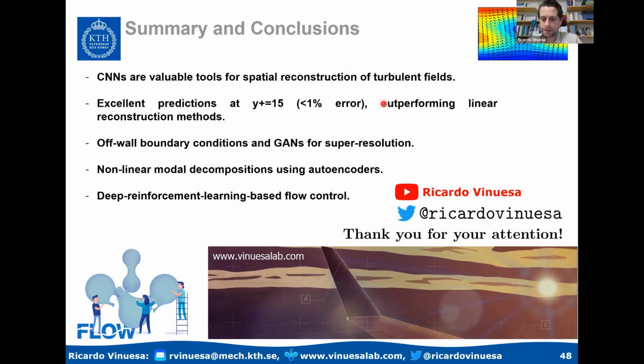Some of these 2D cylinders at high Reynolds numbers that we're exploring become more computationally intensive, because you have many different episodes in parallel and the CFD part becomes more expensive. In that sense, we're looking at more effective strategies for parallelizing this in higher Reynolds number configurations. So deep reinforcement learning is expensive, but I believe there are effective ways to parallelize the effort, at least to some extent.